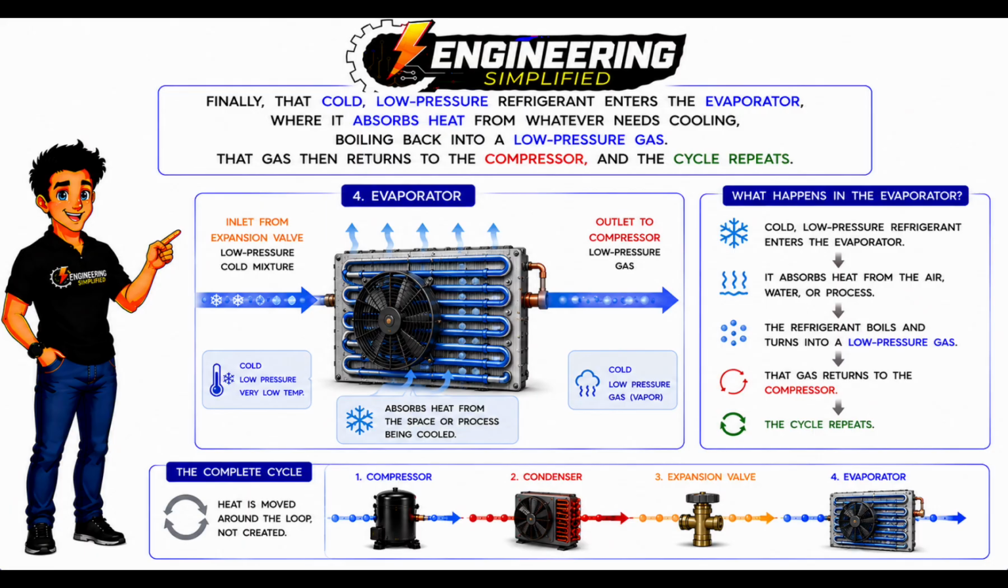Finally, that cold, low-pressure refrigerant enters the evaporator, where it absorbs heat from whatever needs cooling, boiling back into a low-pressure gas. That gas then returns to the compressor, and the cycle repeats.